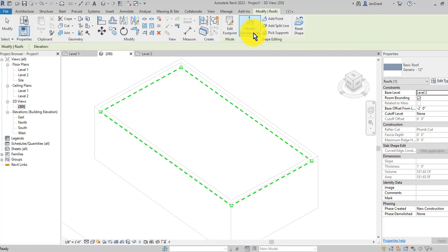So what we're doing here is we're saying that this roof has little boxes that represent the height at those points. So guys, if you wanted to create a roof that was very unique, I've used this so many times to make a roof slope up on one side. There are other tools that we're going to be looking at to do this too. But I had a unique roof that kind of curved and also was lifted. So I drew it as a curve, and then I lifted the end, and it kind of curved and lifted at the same time by using this.